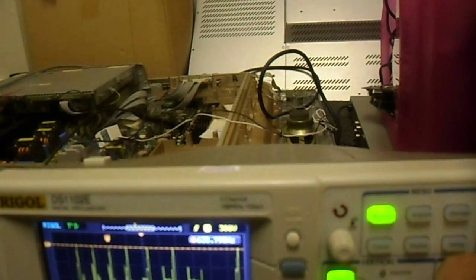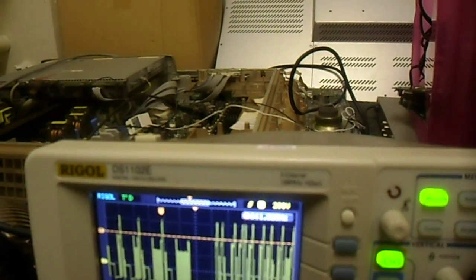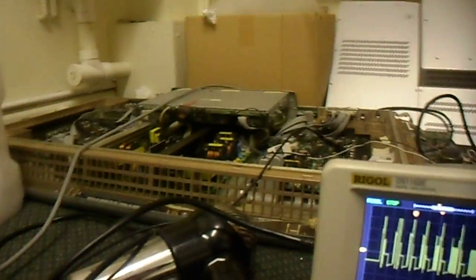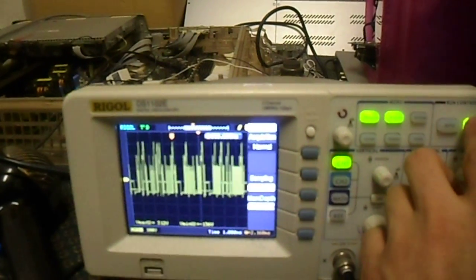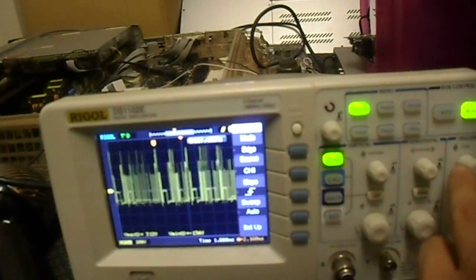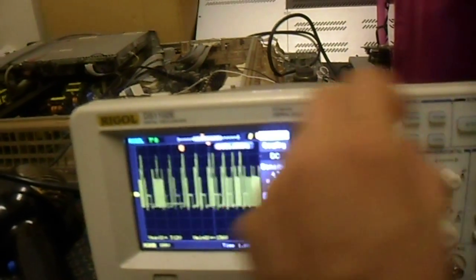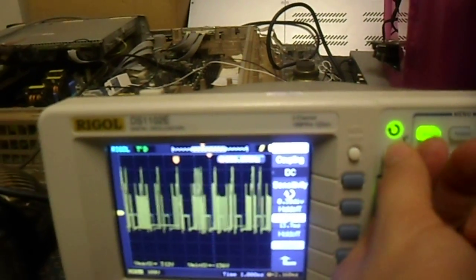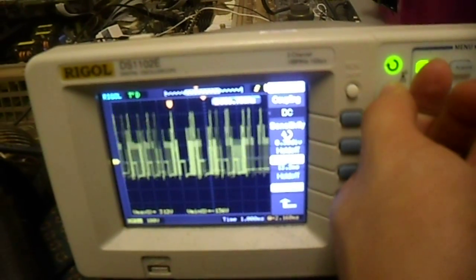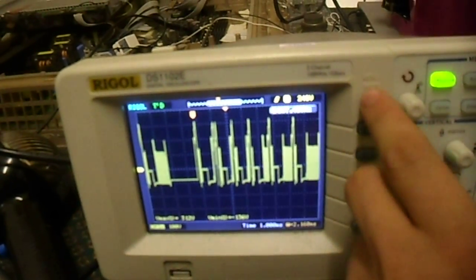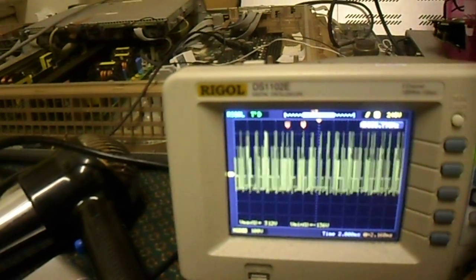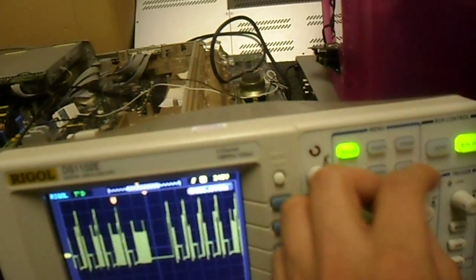It's a bit unstable. Sometimes altering that can help stabilize it. Of course, single shot is always an option. Go into acquire, turn memory depth onto long, do a capture. Again, because you've triggered, the triggering has changed, you're going to have to alter one control to get a stable trigger. Let's see, there we go, stable trigger there. So then you can zoom out, scroll a little.